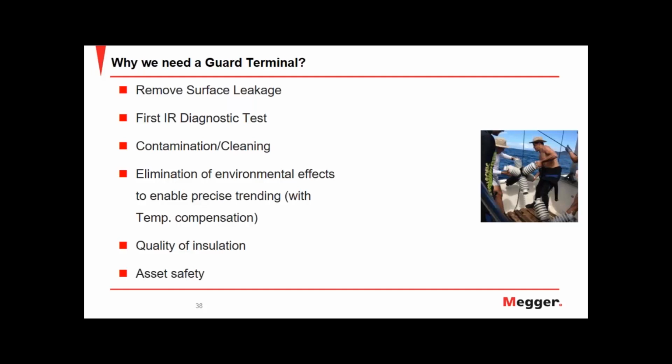Now, in addition to the IR tests, if we perform DAR tests, the dielectric discharge test, or the polarization index test, the step voltage and the ramp, as we perform more and more of these tests, we get a more and more holistic view of the insulation material's quality.